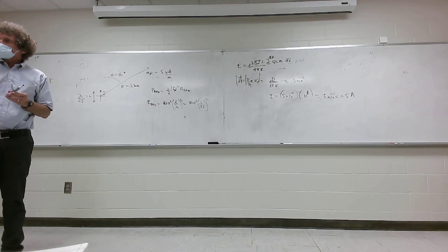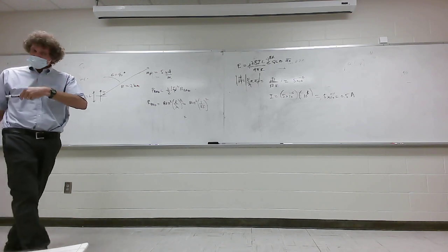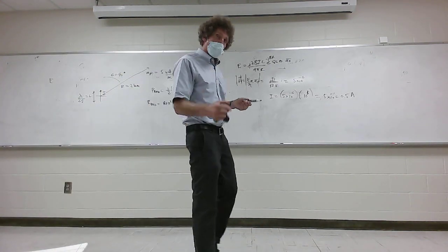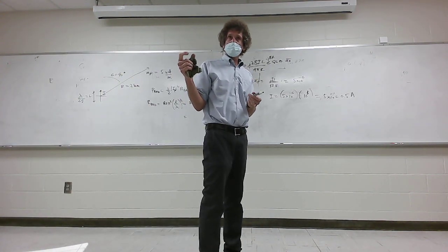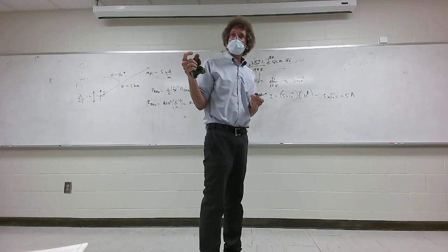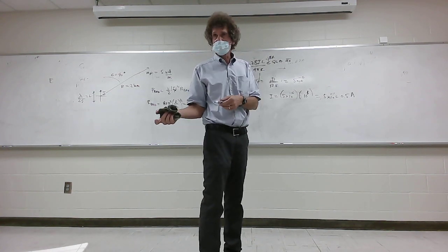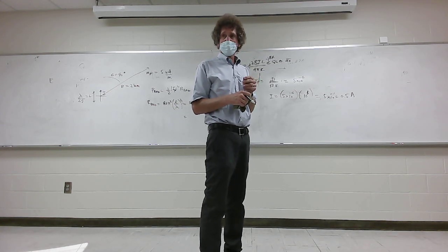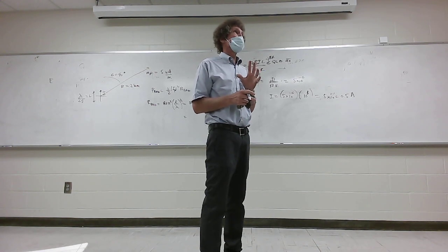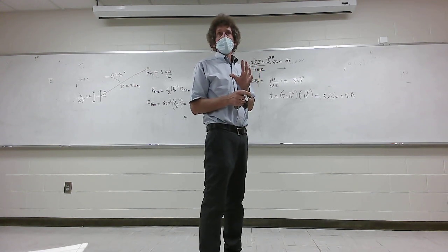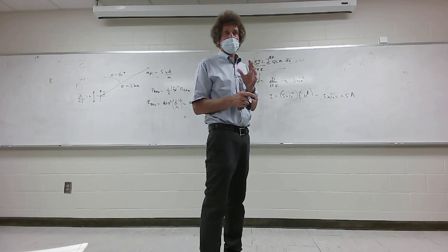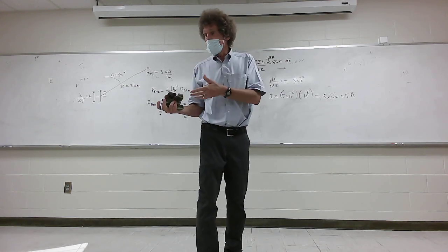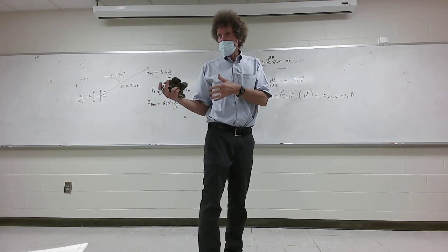Last thing I'm going to touch on right now, not related to the quiz. We've done short dipoles, and I've shown you that the small loops have the same maximum directivity, and that the fields themselves have a radiation resistance that's rather complicated. I think it has 320 pi to the 4th, and an S over lambda squared. By the way, that formula is not common. Wentworth has it, I don't know where he got it, but I'm not seeing it in my EMC work or my radar work, so that's not a common form.